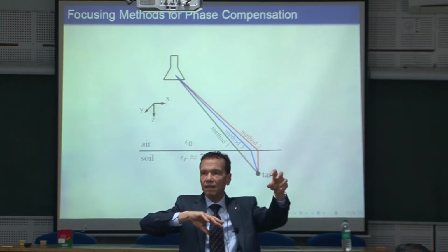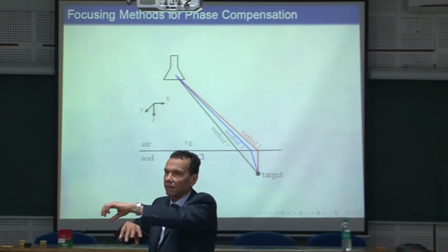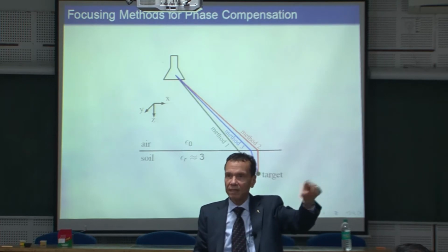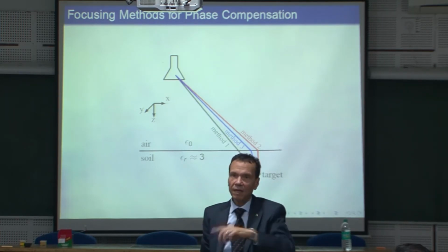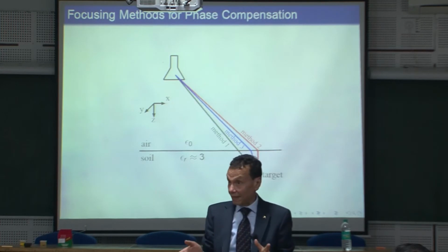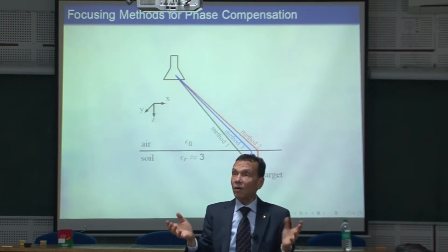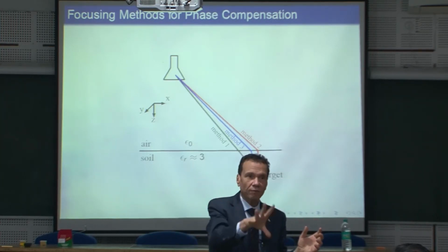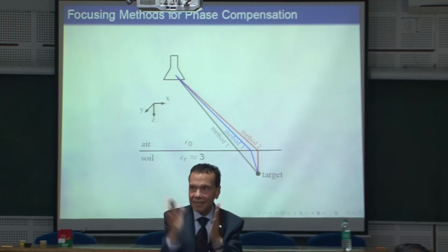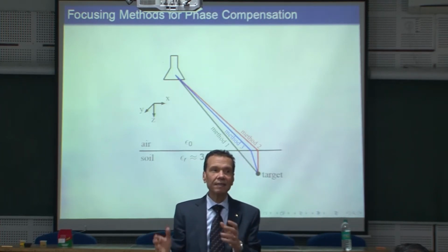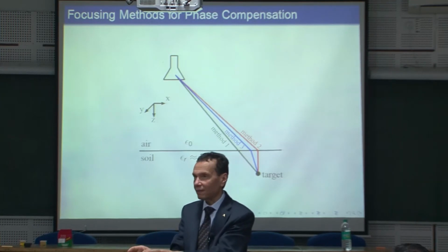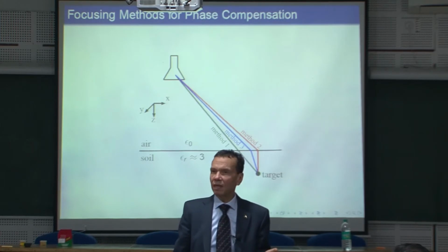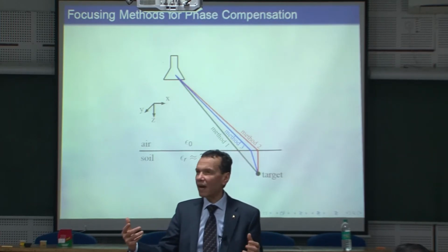If you can measure here, there, and you know actually the distance, the delay, because what you measure here is delayed differently from here, from there, from there. So now you measured and you know the delay exactly, and now focusing means, okay, I will delay this by an amount, another amount, third amount, fourth amount, and so on, so that if I add this together, I get the maximum from this point, and all others contribute by null, by zero. This is one of the explanations of how to focus.